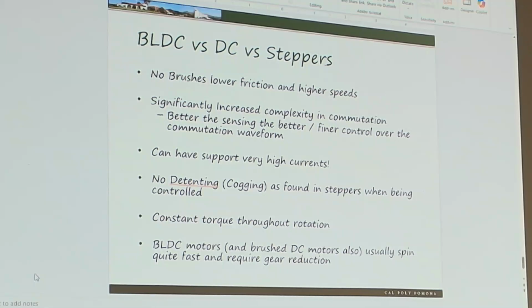But the question I'm going to ask you is, if you don't need the complexity, don't use the complexity. If there's no reason for a BLDC other than the fact it's cool, that's the wrong reason. Okay? DC is just as good for most applications. Yes, I know most drills have BLDC motors now, with a little driver chip from TI, more than likely, or Infineon or a few of the other ones.